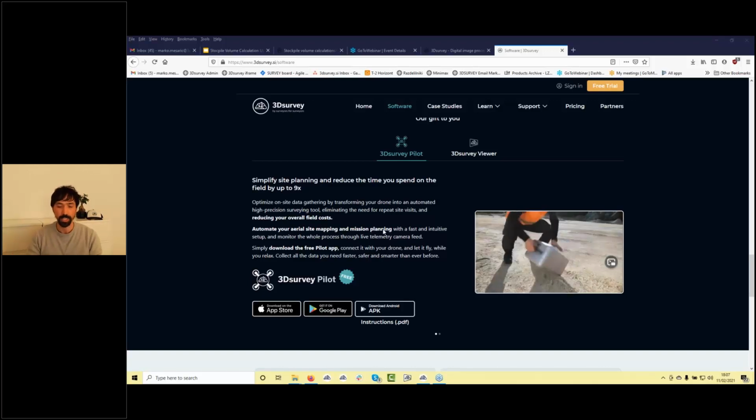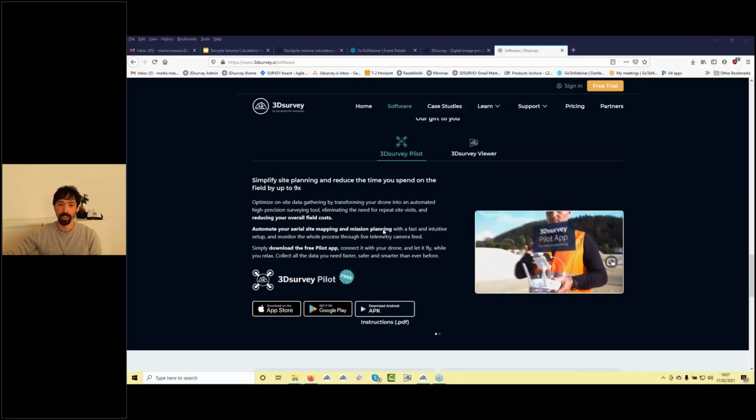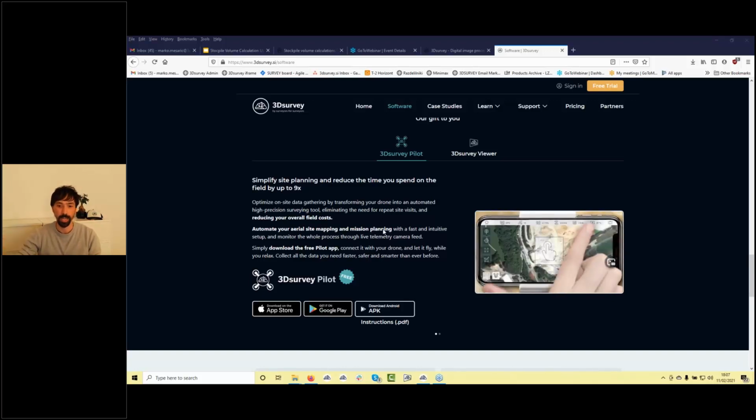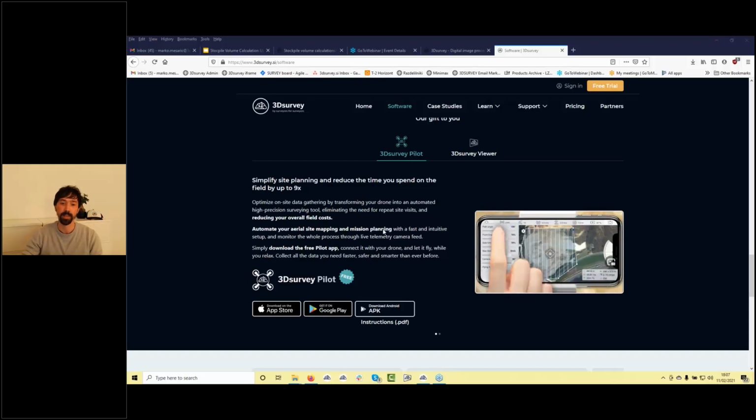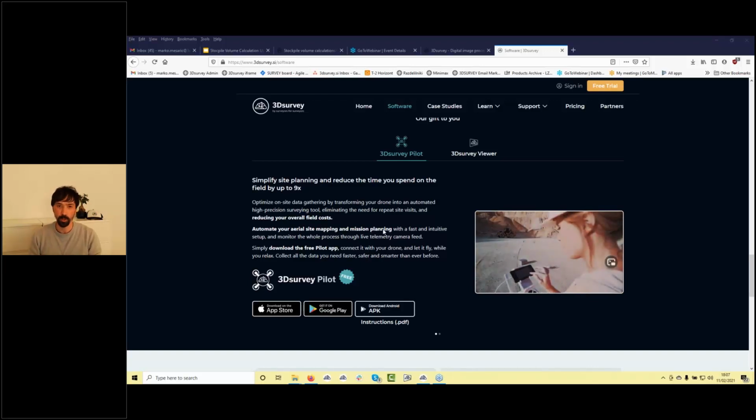Of course, it also works with the Phantom 4 Pro, and just for comparison, if you have an area like 1 by 1 kilometers, with the Phantom 4 Pro you would probably need 20 ground control points. With the Phantom 4 RTK you need, in the best case scenario, just 4 control points in the worst case. In most cases, just a single ground control point helps you with the calculation.